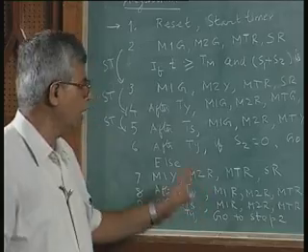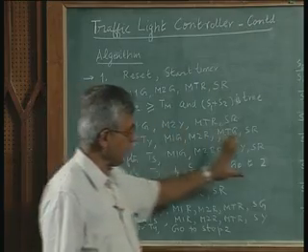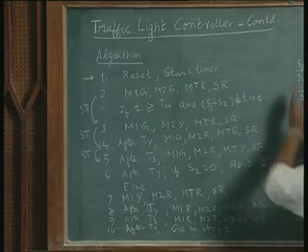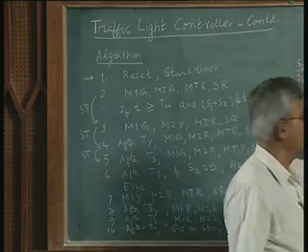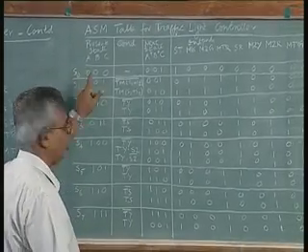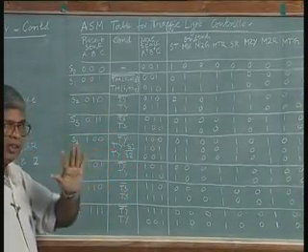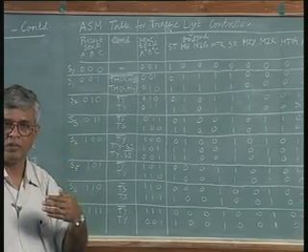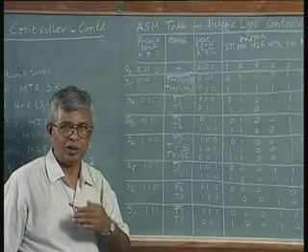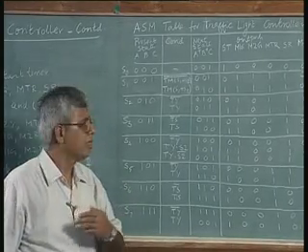Okay. Now, with this you go to this table. You are not expected to memorize this table, it is a huge table as you can see here. There are states here S0 to S7, each state we have taken a binary assignment, it is called natural binary assignment, run without any specific guideline for states.